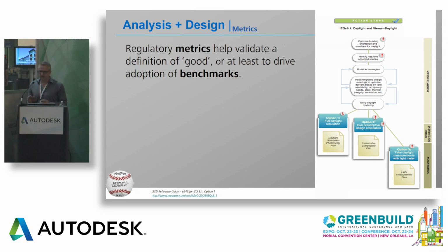We wanted to start out with a tool that automated a process that a lot of architects need to do, and also integrates illuminance data into the design process. So we started out with the LEED metric for daylighting. LEED has both a metric, illuminance, that they measure on a work plane at 30 inches, and a benchmark threshold to pass LEED.